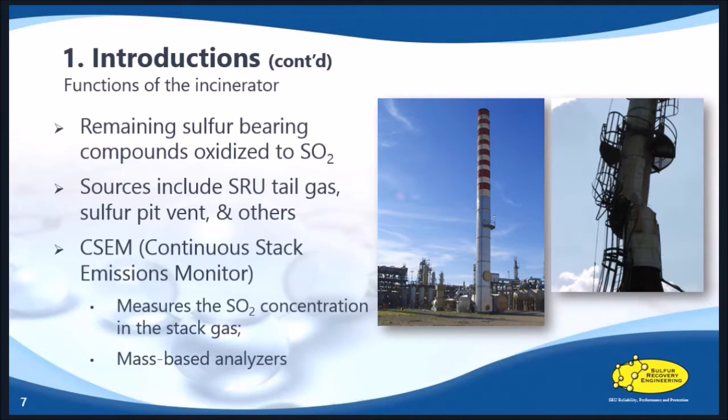There are primary and secondary air supplies provided to the incinerator. And to get the optimum operation of the incinerator, we are targeting excess air at 2 to 4% at the stack outlet. However, most of the time we noticed there was poor control on this front.